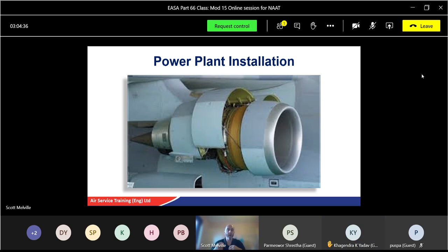The pilot can then press a button, which will give a charge to that, which will literally burn, hence fuzz, burn the debris away. If it's small debris, the light should go out. If the light comes back again, that means there's a lot of debris. But if it's just a little bit of swarf, a little bit of build debris, you can burn it away basically, and it should go out.